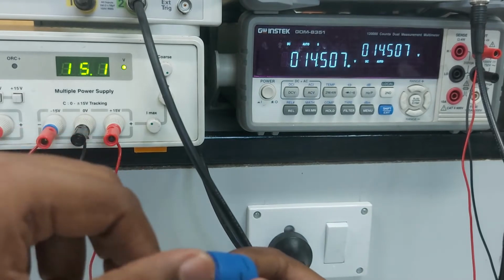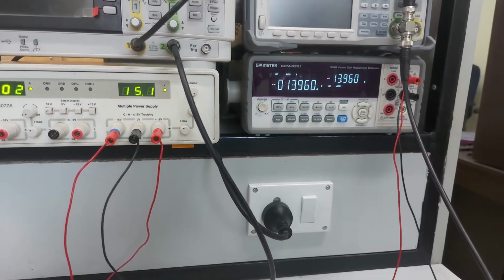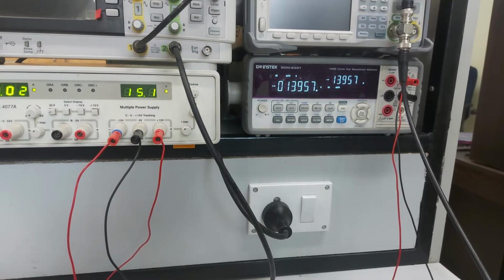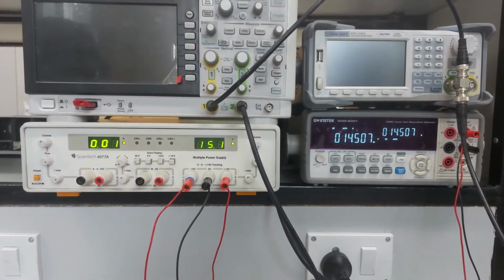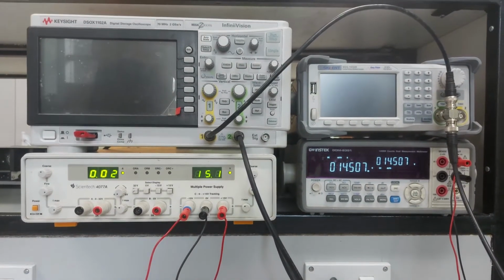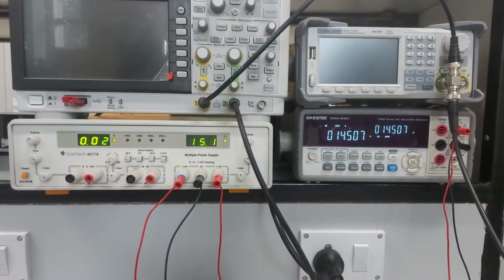Because of the high gain at the input. The op-amp has an open loop gain. So how will we do the offset null right now? One thing I can do is reduce the open loop gain, reduce the gain of the amplifier. How will we do it? By applying negative feedback. So I have two resistors for that.